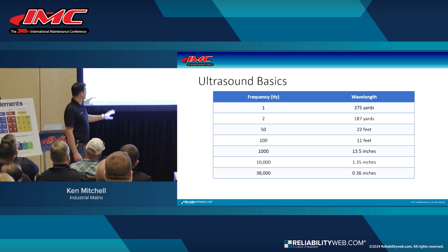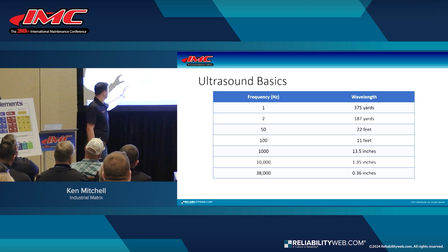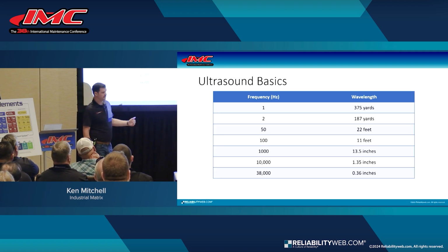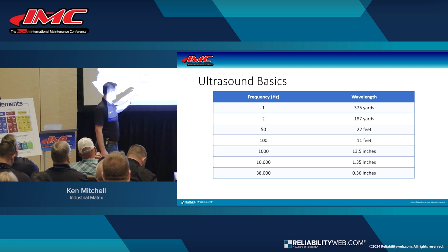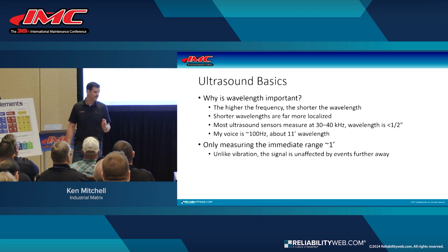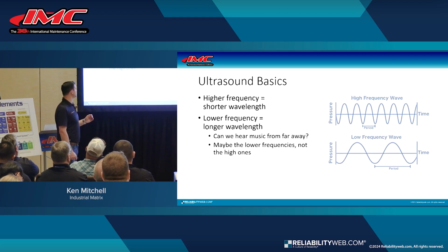The wavelength at around my frequency of voice, I'm probably talking around 100 hertz, is going to be feet, or at least quite a few inches. As we move up into that high frequency band, specifically ultrasound, that wavelength comes a lot closer together. And the reason why we use that tool is because higher frequency wavelengths are much more localized. So we're not, again, picking up what's going on further down the machine.